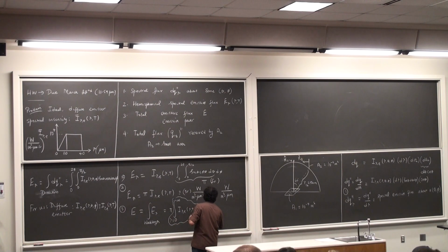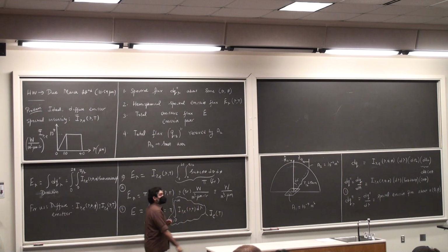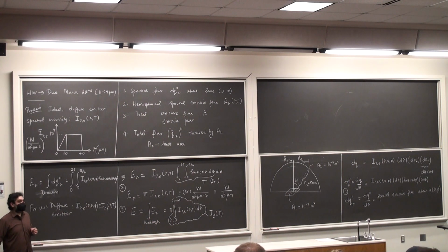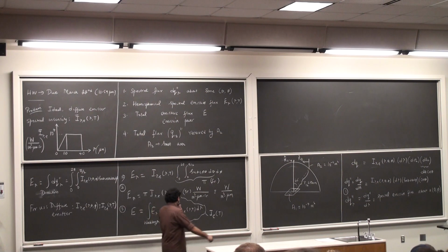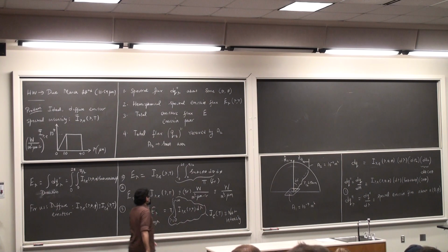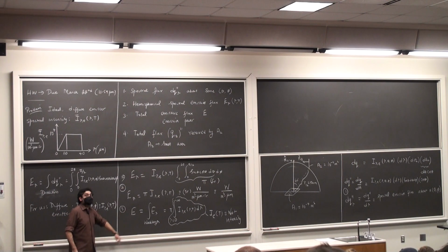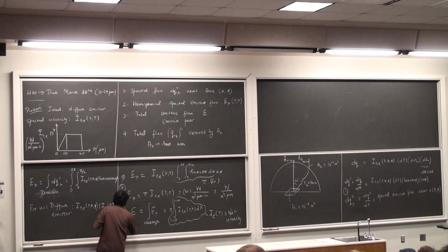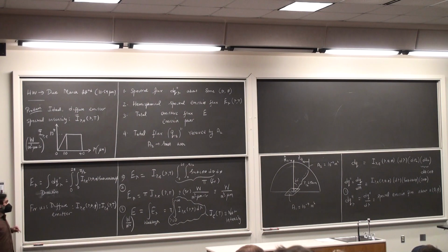as IE, which is the net radiation intensity, okay, or the net intensity. All right, and then eventually the units will be for emissive flux, which is watts per meter square. One can easily prove that. I'm not going to do it. I'm just taking E lambda, which is dependent on micrometers, and then multiplying it by d lambda, which is micrometers, so I'm left with watts per meter square.